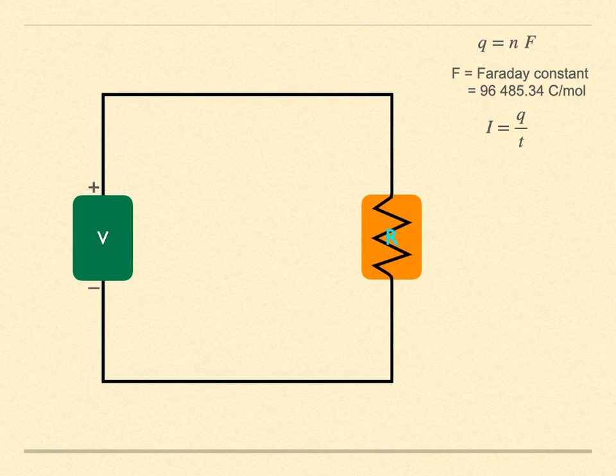The difference in electrical potential is the key to having a current of charges flow around the circuit. If there was no difference in potential, no current would flow. When a charged particle moves between two points of differing potential, energy is released if it is going from high to low potential. And if we have a device that pushes the charged particles in the other direction, energy has to be injected into the system in the form of work. The potential difference is measured in units of volts. We often use E as a symbol for this electric potential difference. When a charge in coulombs moves through a potential difference, the energy released or absorbed is measured in joules. It is also common for the potential difference to use the symbol V as well as reporting its value in units of volts, which also has the symbol V.